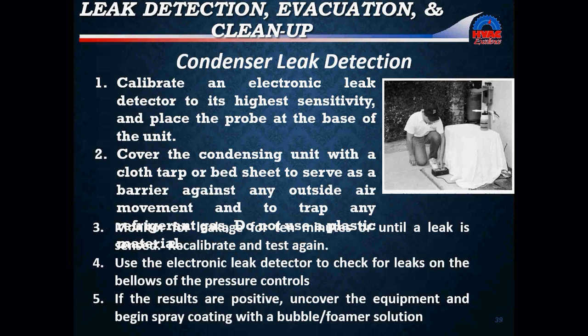Because again, refrigerant is heavier than air. It's going to settle. What you're going to want to do again is make sure that the leak detector again has not been subject to water or any sort of debris or dirt.